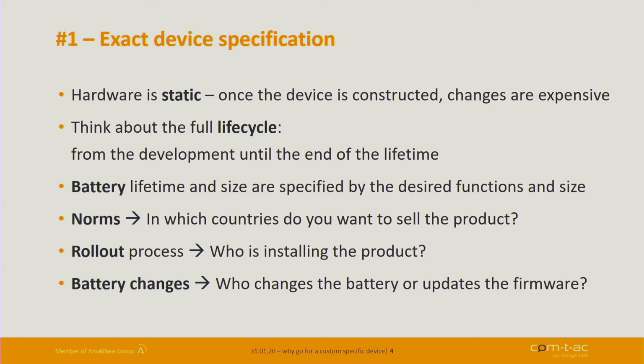Another important thing is the norms. We have the regulatory requirements, especially for worldwide applications. The LoRaWAN ISM band is regulated differently depending on the region where you install the device. That's important when you start the development phase, and we have to take into account how we optimize the payload and everything like that. Very important too is the rollout process. Device cost is one thing, but you also have to install it and maintain it over the full life cycle, maybe change batteries, make firmware updates. It's important to think about that when you start with the design.